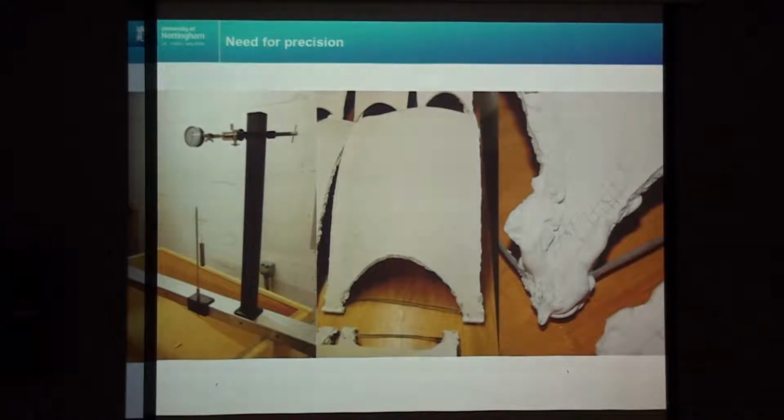And in discussions with him and in all his papers, the thing that he emphasized most greatly was that you need absolute precision when you're measuring the forms. When he was using the hanging cloth reverse method, he eventually ended up with a cast, plaster cast, and this is the jig he measured in, and you can see here on the surface of the cast, that's the grid that he measured all these points, and he said he was measuring those points up to 10 or 12 times at each position.